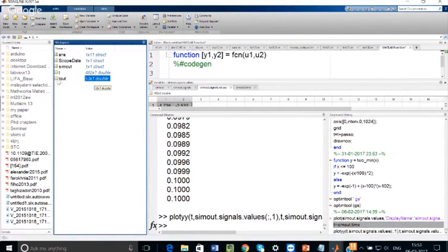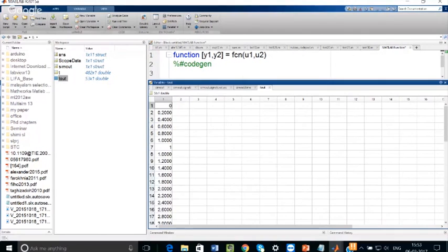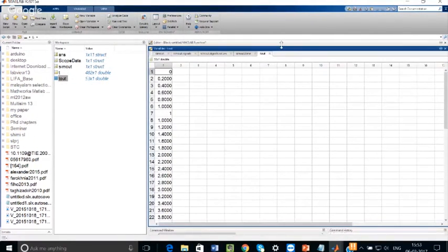Why 53 samples? If you had connected a constant, it would have given only 51 samples, because here I have kept 10 seconds, 0 to 10, so it is 10 minus 0 divided by 50. Always it is 50 steps in one simulation; that is the MATLAB default. So in this case, what happened? There is a change in 1 second, a change in your unit.